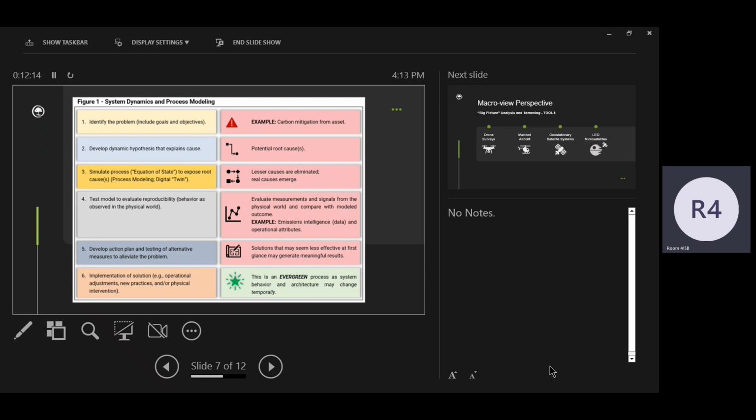We had this one LDAR project where the facilities that we monitored had some pretty consistent leaks across the facility. We saw them coming from the same thing at every facility, and it was a pneumatic tubing insert that went into a controller. At that union, at that interface, in literally every one of these facilities, there was a leak. We tighten it, we inform the repair crews, they go, we tighten it, no resolution. So we applied kind of a root cause analysis following this model. What we ended up determining was that the reason it was leaking in every instance is they were using Swagelok nuts and Parker barrels.